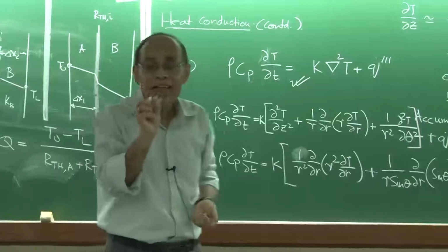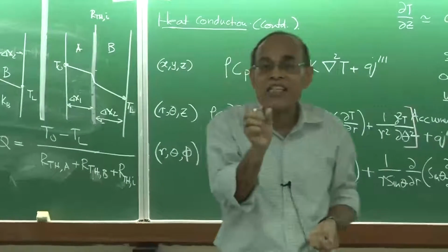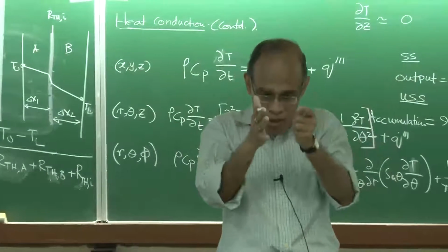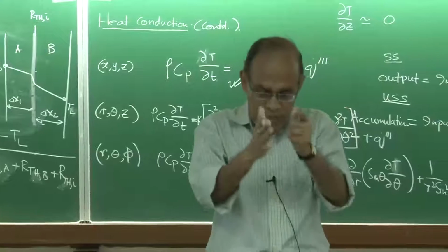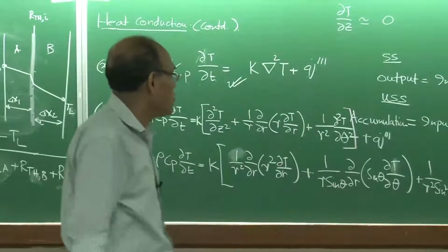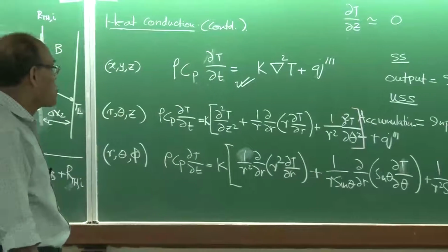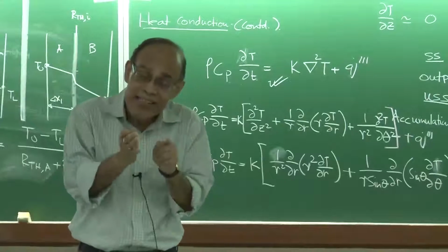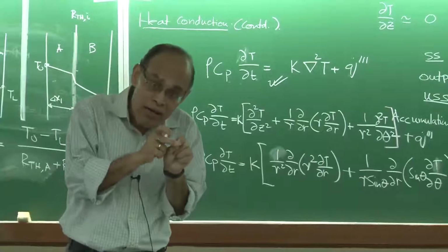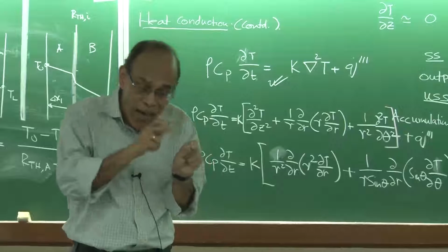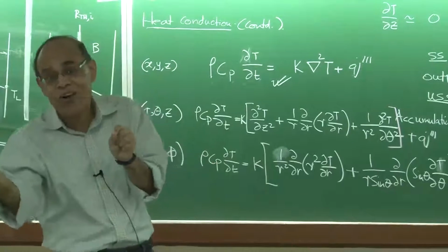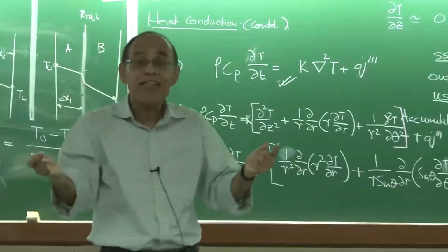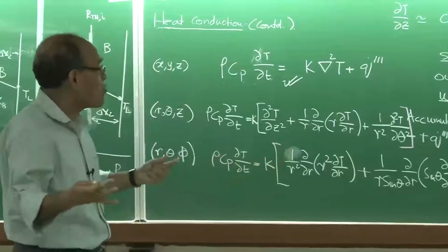So, that basically is like a resistance between the two surfaces. It is not an air filled space between the strand surface and the stationary mold, but the space is filled, and you have a powder mold contact on one side and a powder strand contact on the other side. And the characteristics of these contacts are different.